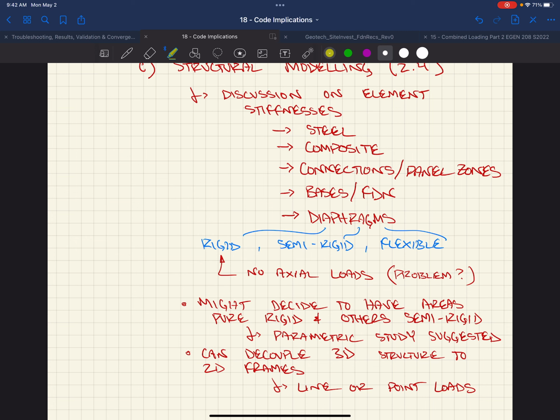Panel zone. This one is cool, okay? This is diaphragms for three-dimensional analysis, okay? What are they saying here? Well, they say all sorts of cool stuff about the stiffness of it, how you model it, the negatives associated with it being a rigid diaphragm. A rigid diaphragm model prevents relative in-plane movement between nodes on a given floor. Any ideas why that could be bad?